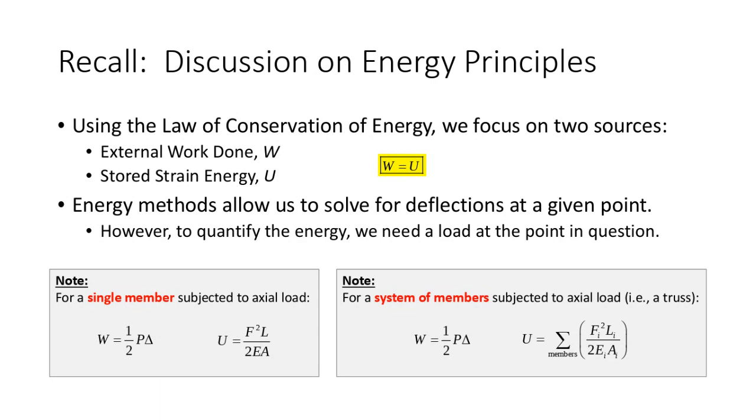A very common deflection limit we use in structural engineering is L over 360. We take the length of the beam, divide it by 360, and say you can't deflect more than that. Where do you come up with that? Well, the idea is that if it deflects more than that, you'll start to crack the plaster. That doesn't mean the beam's going to fall down and kill somebody, but the beam is certainly not performing its intended function. We don't want the plaster to crack. And so there are some physical reasons why we want to understand deflections.